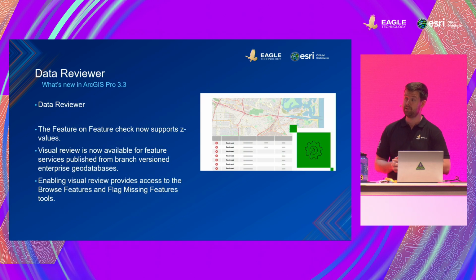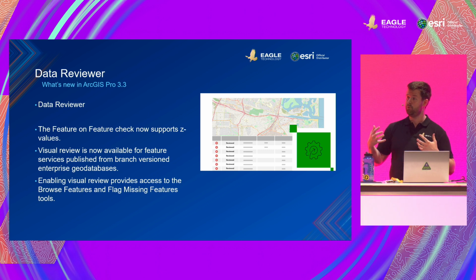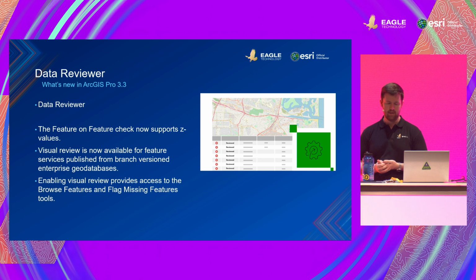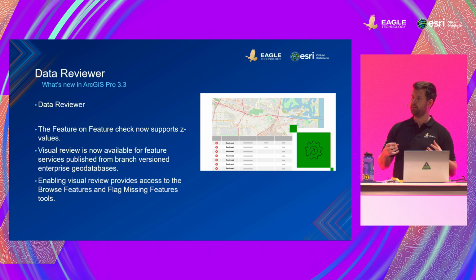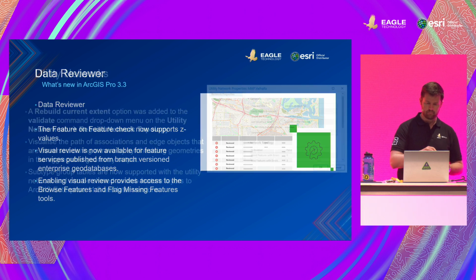And a really useful tool for this is Data Reviewer. Anyone using it in their organisations at the moment, Data Reviewer? What's pretty cool is it does three key things. You automate error detection in your large complex data sets. You can engage others across your organisation to do that review for you, other desktop users of Pro, and then also track and manage those quality updates. So it's just an additional tool in your toolbox to be aware of if you are requiring maybe peer review of maybe conflicts and edits in your data sets. And I think it's a pretty neat thing to explore.